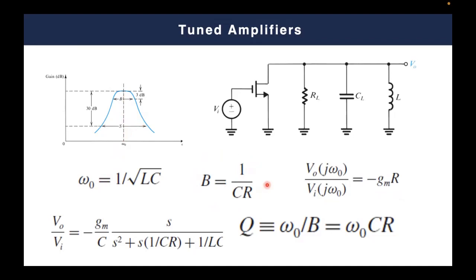And accordingly, we can define what's called the Q factor. Maybe you will consider this Q factor later on in your antenna classes, and also I believe we have it somewhere in our optical classes, which represents the sharpness of our response. So ideally speaking, if this band pass filter is an ideal impulsive filter, I mean you have a single frequency only passing with 0 bandwidth, then this Q will tend to infinity because simply your bandwidth is 0.